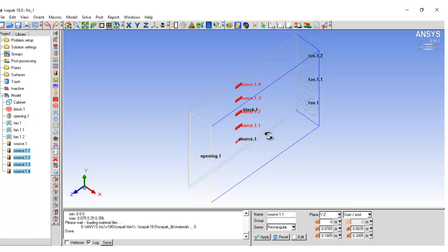And then we will build some heatsinks, and in this case this is one of the methods to build the heatsink. We create one piece of the heatsink and copy it to get more. In the next video, or in another video, I will introduce the other methods, so you can choose which one you like. Now we choose the create plane button to create a plane, and we can find inside the center of the window there is a tiny plane.